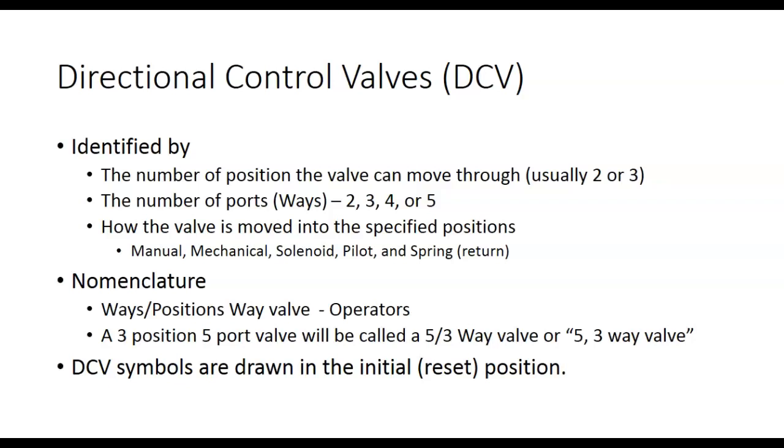When we draw the valve, we draw it in its reset or power off position. So that would be the way we would draw it on all the lines back there. That's where they'd be drawn when we draw the diagram. We okay? We're okay.